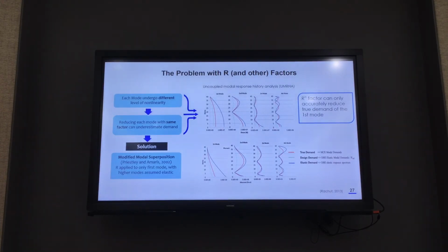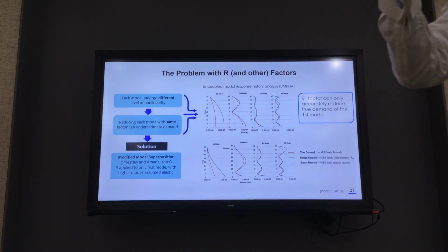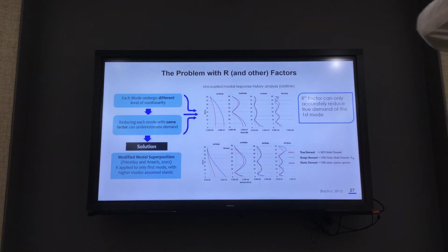So normally, as I might have mentioned or not, when engineers design the building and bring it to us for performance-based design, the first thing we do is take the vertical reinforcement from the shear walls and put it horizontally. And we take the horizontal reinforcement from the beam, reduce it, and increase shear without doing anything else. If you just do that, your structure's performance will increase without increasing cost.